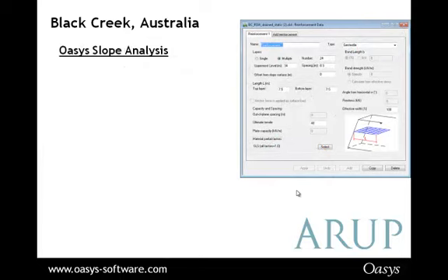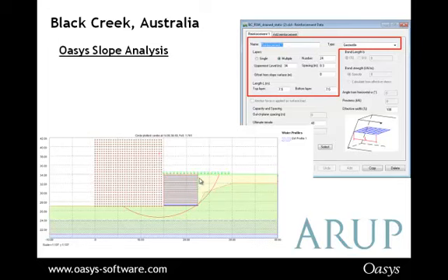So the reinforced wall was represented by multiple geotextile reinforcements, and as you can see here, this is the reinforcement section in Slope. So we've chosen geotextiles, we've chosen various levels, and I've clicked on the multiple here, and the length is shown at the top and the bottom layer, which is constant. So this is shown here in the Slope graphical output. And as you can see the multiple geotextiles shown, and the spacing is 0.3 meters as is entered in there. And as you can see at the top of the graphical input, we've got an acceptable factor of safety of 1.761.